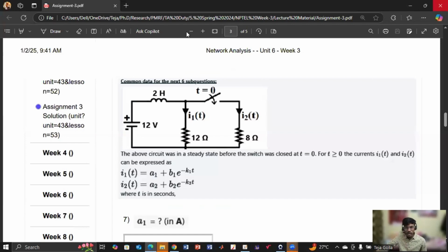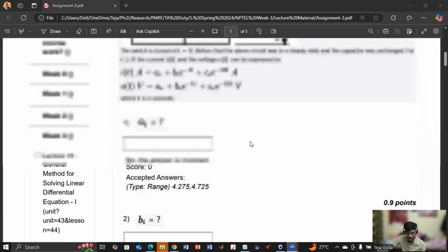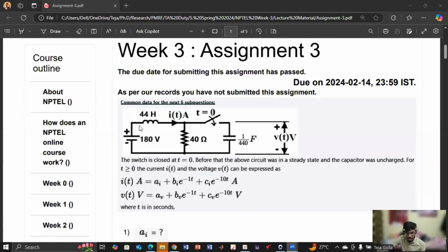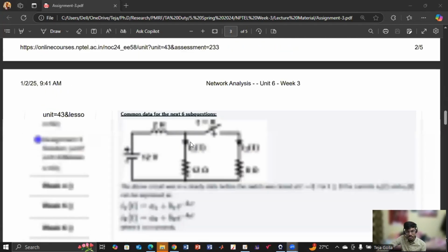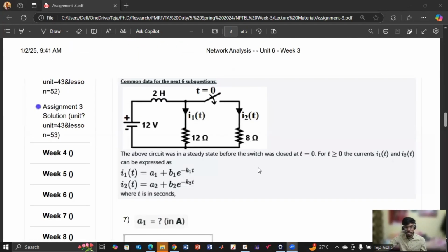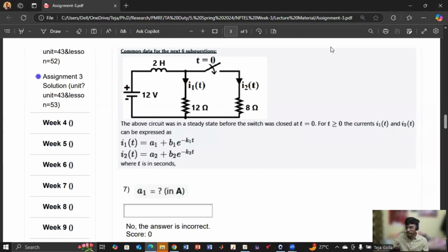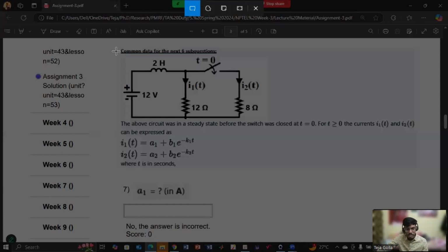Okay, so we have around half an hour left. So now this is like first order. If you see, looking at the circuit, you can tell what is the order. You have to count the number of inductors and capacitors. So here it is two, right? Inductor and capacitor. So it is second order. And here it is one. So that's why it is first order. So very simple because they will give either one derivative or one integral, right? Resistor, it is just a direct quotient.